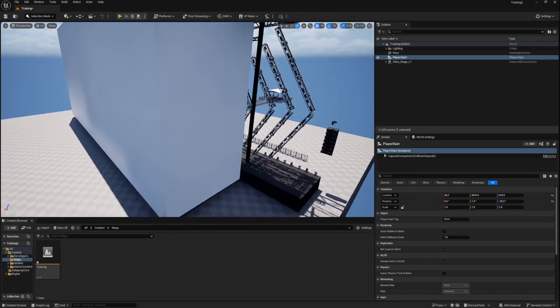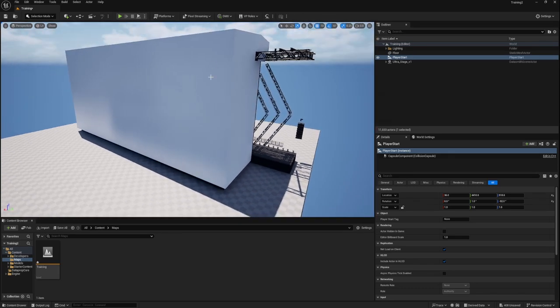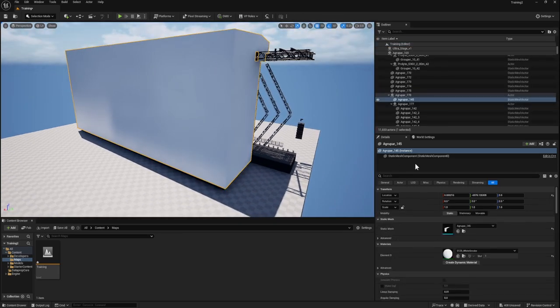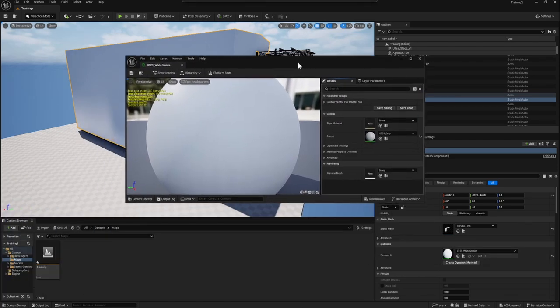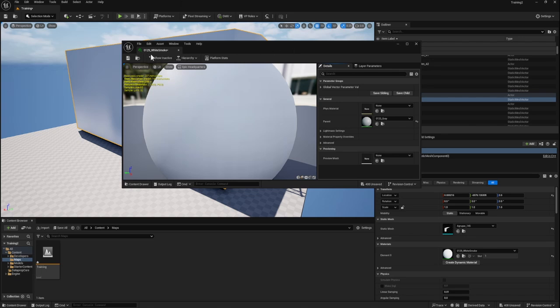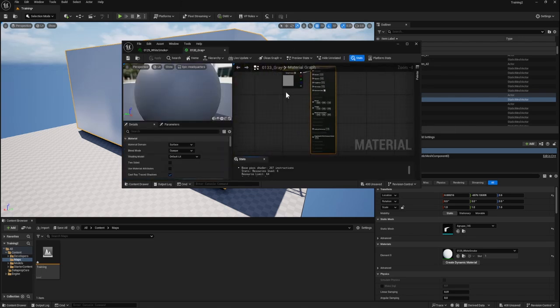This is actually a really super easy way to change this. You click on the surface, you find its material in the right-hand corner here. Click on that. Now, it might be a material instance, which is something different, which I'll go into later. But for now, we want to go to parent. And you will see here on the left-hand side, two-sided. And we want to click that yes.